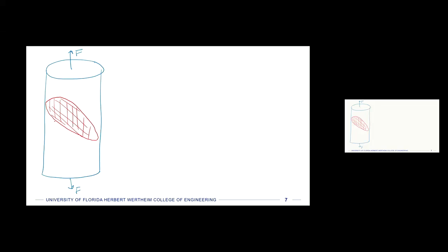And if we were to draw a normal to that plane, here's my normal arrow, right? Then that would exist at some angle away from the force that I have applied, and we're going to call that psi. Okay, that's what the book calls it, so we're just going to go with that. And so psi is the angle between the applied force and the normal to the slip plane. Okay.